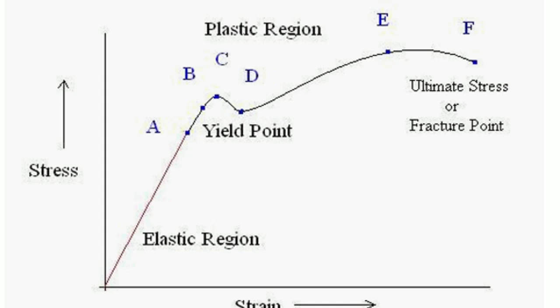So here it is, from O to A, the stress is proportional to the strain and the material obeys Hooke's law. So whatever the strain is generating, that is proportional. So we have no problem. Now, what is portion A to B? In this portion, Hooke's law is not obeyed, although the material may still be elastic.